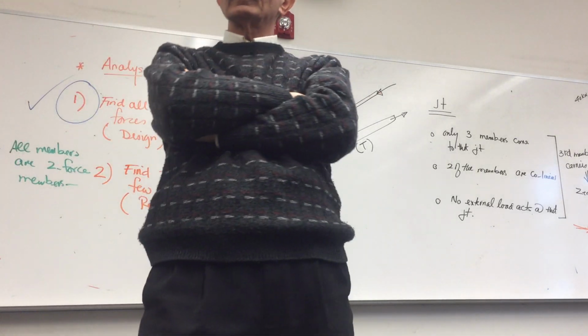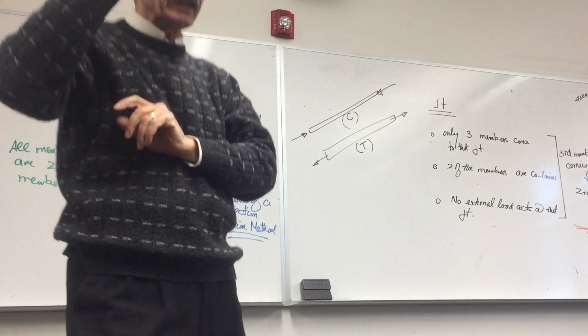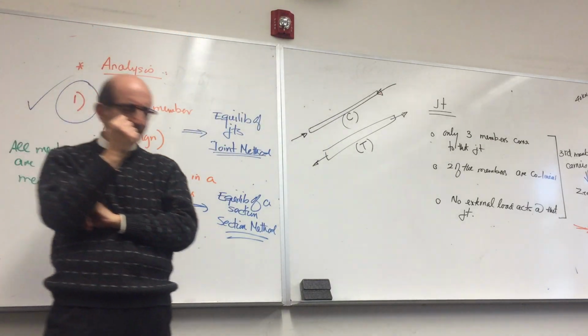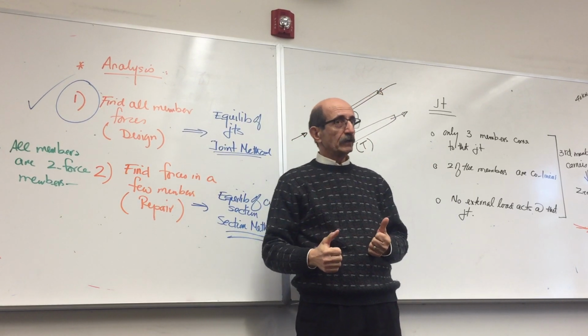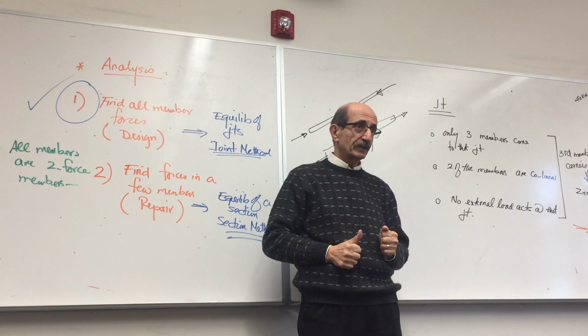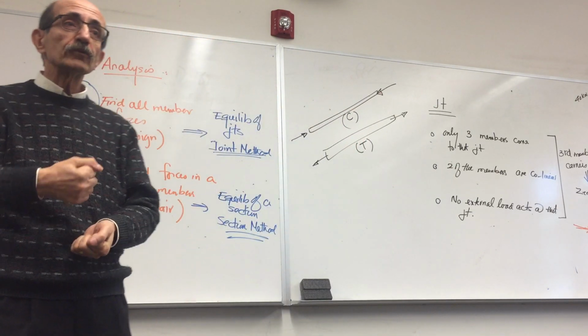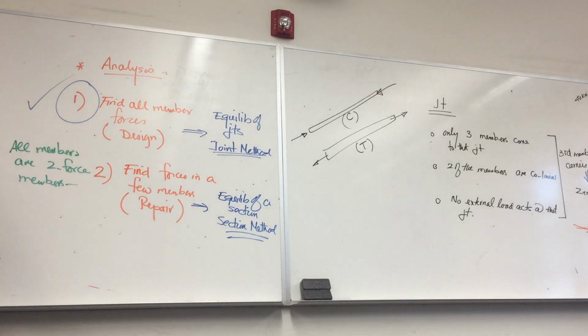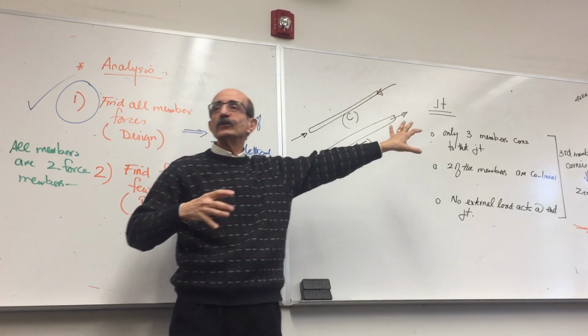Because if you put a force at where those connect, then it won't be a 0 force member. See, you said it. 2 points. I think you deserve that. Okay. See, the 0 force members are not a property of the truss. They are conditions that result from the type of loading that the truss in that particular loading case is going to carry.